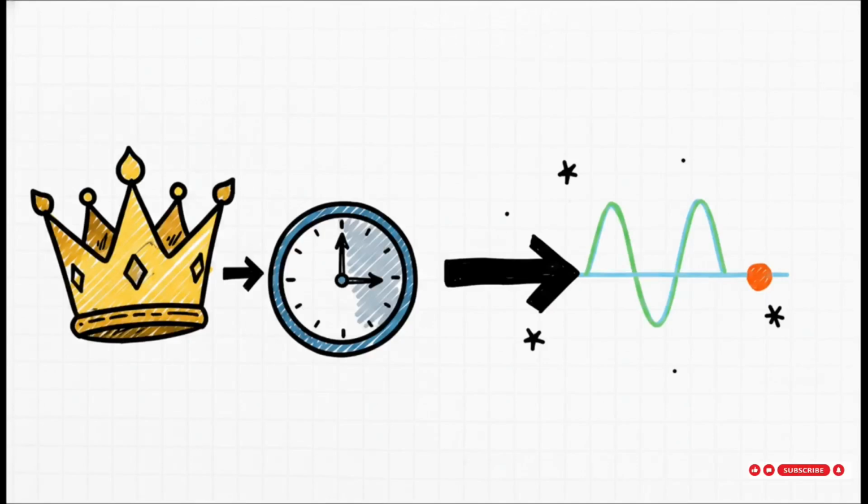And what's wild is how simple the math actually is when you look under the hood. That lowercase e or i, that's your instantaneous snapshot. The uppercase Em or Im, that's our anchor, the boss maximum value we just nailed down. And that sine of omega t is just the changing time angle, which you'll sometimes see written as theta. Notice how the instantaneous value totally depends on taking that maximum peak and multiplying it by the sine of whatever angle the wave happens to be at. Like I said, it always comes right back to the boss.